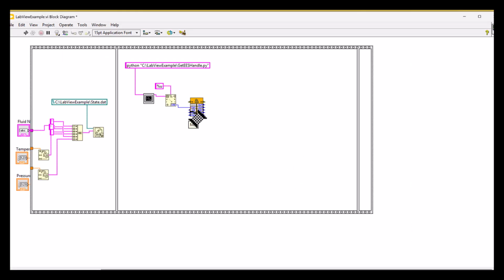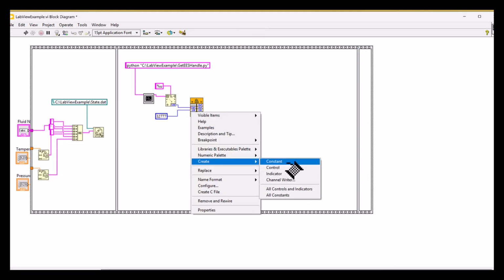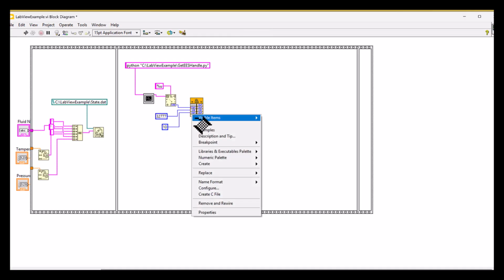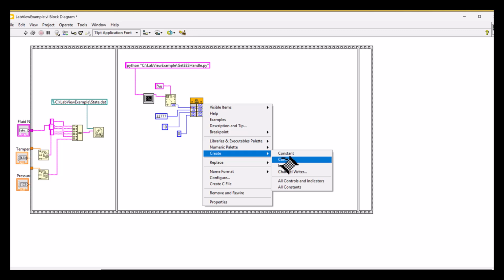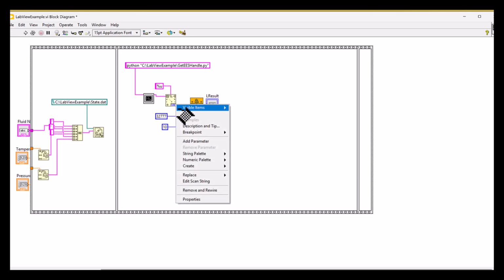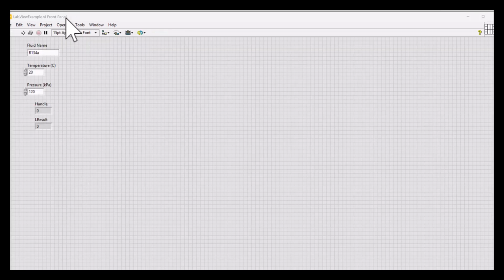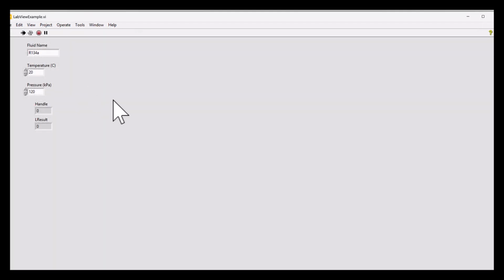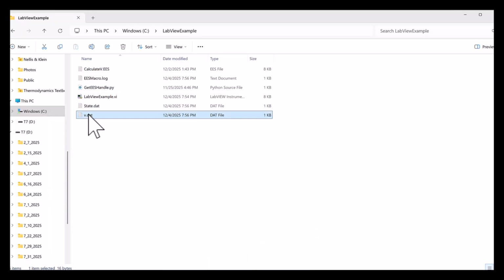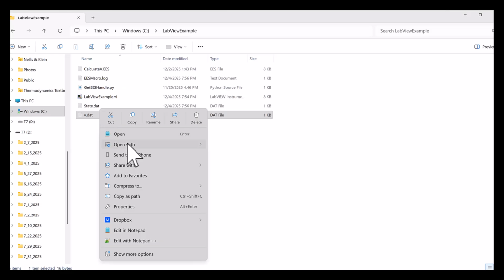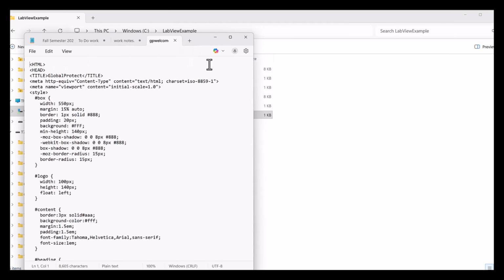So let's go ahead then and wire the Windows handle to the first input, and then in sequence 32777, 10, and 0 to the other inputs. And let's go ahead and display. So we'll add an indicator for both the Windows handle and the output, the result, for troubleshooting purposes, so we can see that everything's working okay. So if I run now, what I should see is that the EES code solves, and I should also see that a file v.dat has been created. And if I open that file v.dat, that should contain the specific volume that was calculated from within EES.